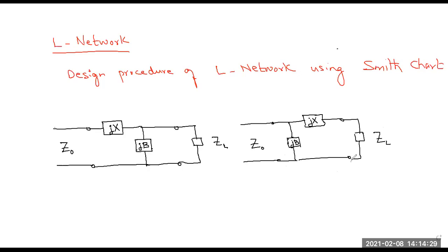This is something we have covered. Whenever we connect any element, whether capacitor or inductor, in series with this transmission line, we represent that element by its reactance. And whenever we connect any reactive element in parallel or shunt configuration, we represent that element by its susceptance.